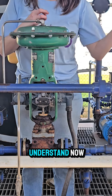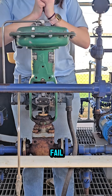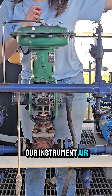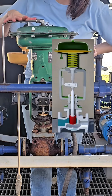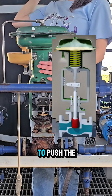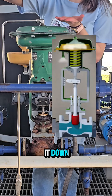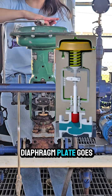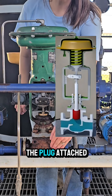We know and understand now that instrument air is what's controlling this. When we say fail, we mean that our instrument air system failed, or our instrument air failed. If we lost instrument air, that spring right here is going to push the diaphragm plate up, because now there's no air pushing it down. So if the diaphragm plate goes up, then the stem goes up and the plug attached goes up.